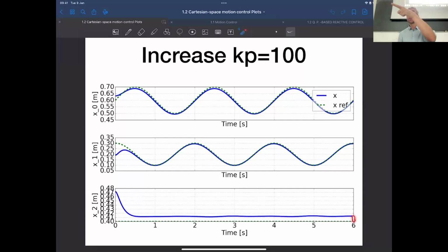And I think in this case, your idea would be really the solution, if we wanted to also compensate for this 1 centimeter error. If it's a constant steady-state error, integral is really the best solution because it works very well for this constant error. For dynamic errors, it's a bit harder because it has this averaging effect that doesn't work well if your reference motion is constantly changing. But since on the z-axis, the reference is actually fixed, it would work very well.